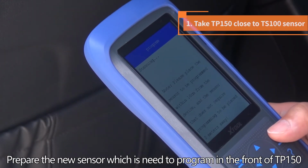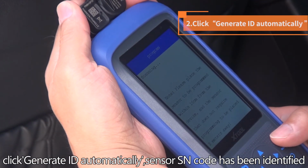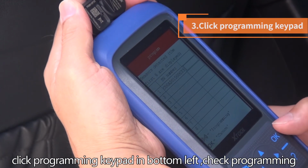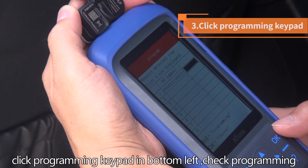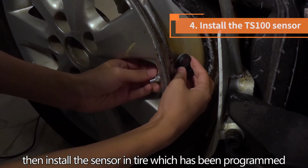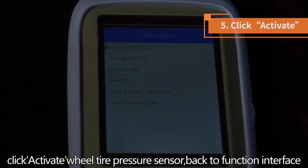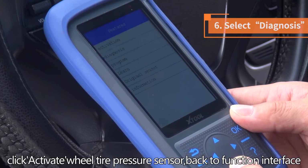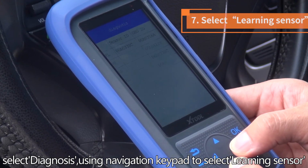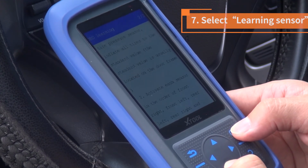Prepare the new sensor which needs to be programmed in front of TP150. Click Generate ID automatically. The sensor SN code has been identified. Click the Programming keypad in the bottom left. Check Programming. Then install the sensor in the tire which has been programmed. Click Activate Wheel Tire Pressure Sensor. Back to the function interface, select Diagnosis, and using the navigation keypad select Learning Sensor. View the hint to learn the sensor.